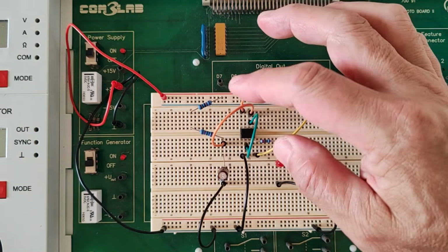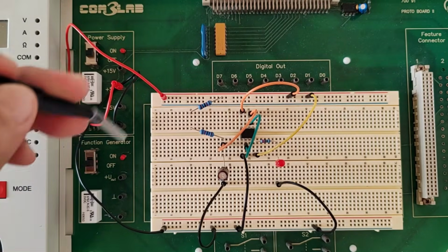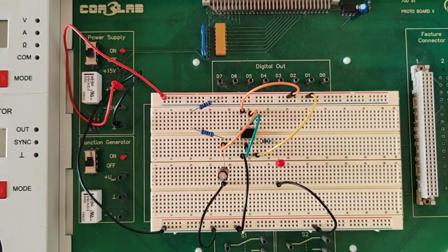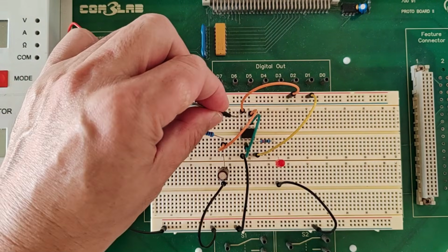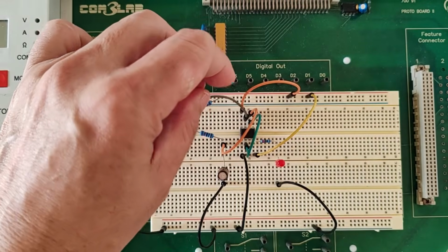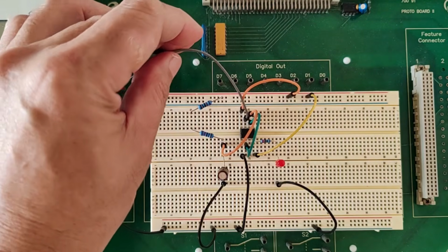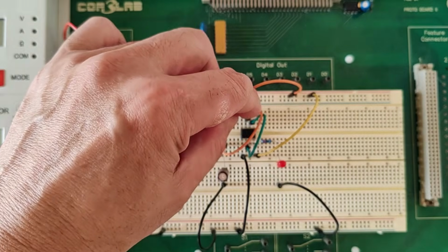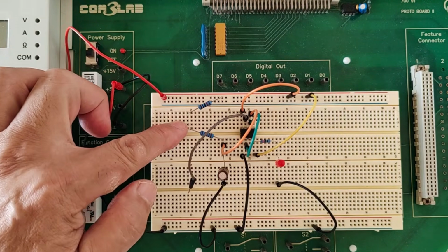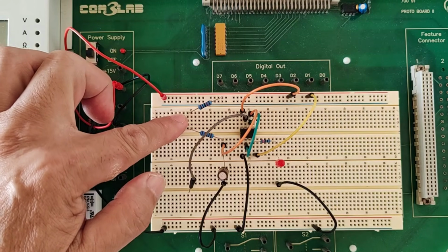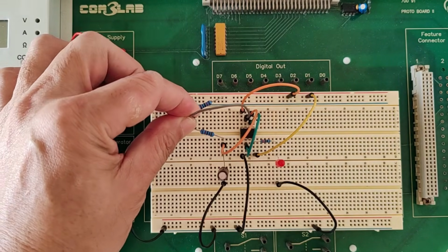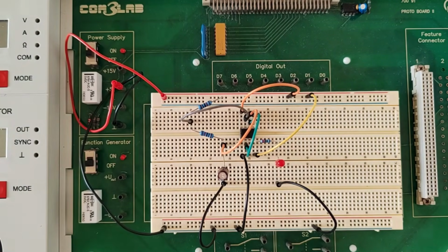Pin number 7 of our 555 timer, this one, will have to be connected via a jumper wire again. So let's have another jumper wire on pin number 7. Put it here, pin number 7, there. This jumper wire coming from pin 7, the second jumper wire, will have to be connected to the junction between the two 10 kilo ohm resistors here. Let's do that now. Connect it here. There.